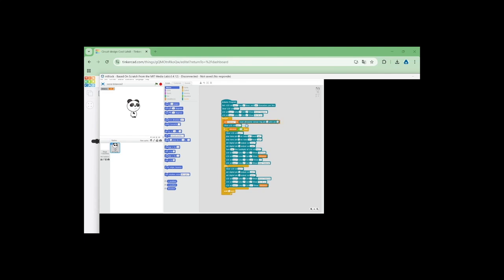First is just cleaning whatever is on the screen. And if the distance is under 30, or under 50, it just plays a tone on the buzzer, sets, depending on the pin we want, digital pin 6 or digital pin 8, turns on the lights, starts writing on the LCD element, and after this, writes a warning: the distance is too close, keep distance. In any other case, we can just clean and say you are in the safe distance.